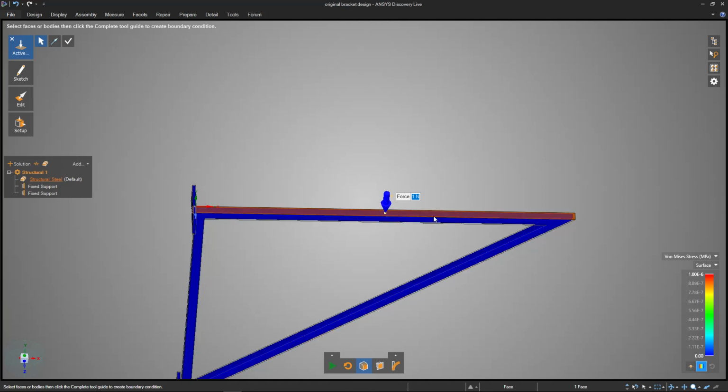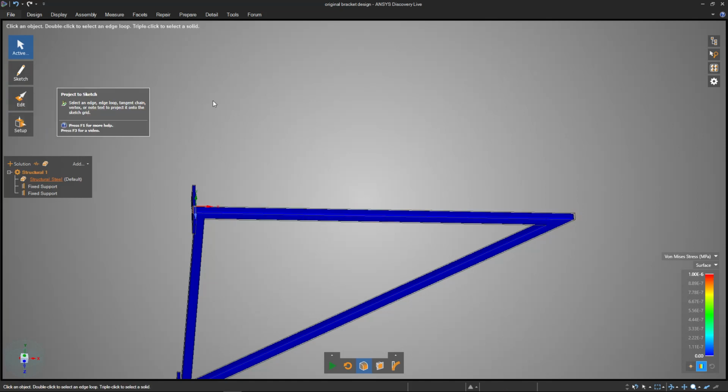So I'm going to hit escape to undo that. What we actually need to do in order for the force to be out here is to define a little closed box. We can do that easily in the sketch menu up here. I'm going to sketch a tiny rectangle on there as the point where the force will actually push down. Hovering my mouse over sketch, I can see it's got a number of shapes that are commonly used. Let's pick the rectangle one.